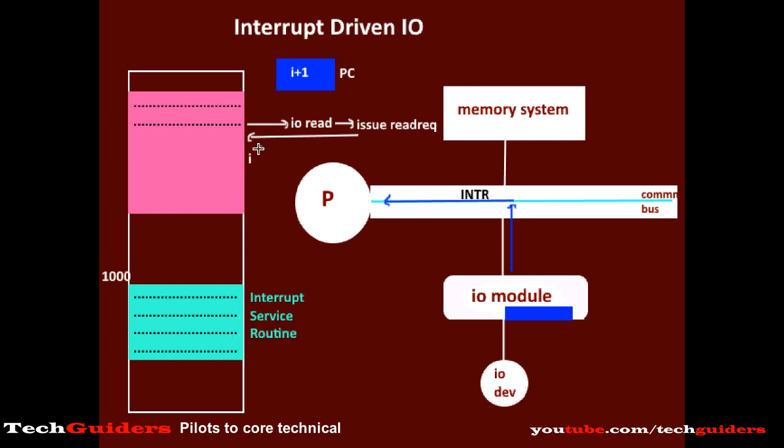Before moving, it will save the address in the program counter, which is the address of the next instruction to be executed, onto some temporary storage such as a stack or a dedicated register. Also, since we are now shifting to an entirely different routine, the current state of the processor will be saved. All the information required upon returning will be saved.